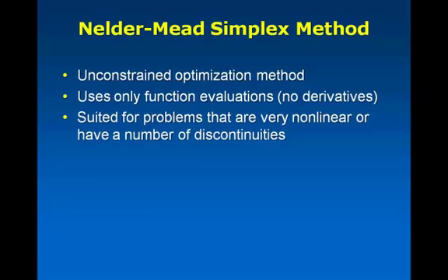And as those of you who have used the activated sludge models, the ASM models, over a period of time have known, they are very complex. They can be very nonlinear in some cases, especially when you're dealing with situations where you're partially nitrifying, where there can be really huge changes right at those borders, and a number of discontinuities, specifically if you're using simulations where you have something that cycles through a number of periodic steps, like the sequencing of an SBR or something.